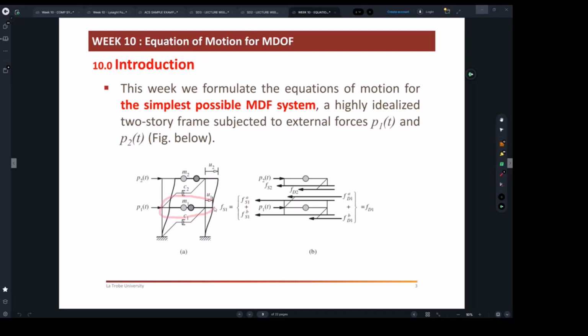This whole floor will move together, because it's a piece of concrete which has to move left or right together. But it's not dependent on the other floor. It does not mean the whole building has to go to the left: if the first floor goes to the left, it does not mean the second floor has to go to the left as well. You've got situations where the first floor goes to the left and the second floor goes to the right.